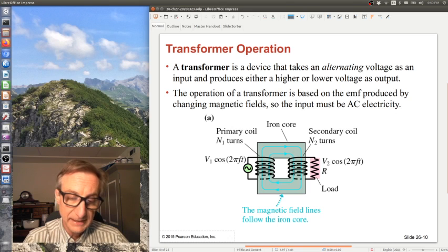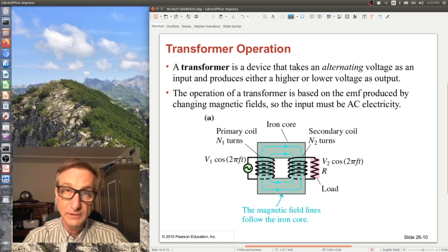So as the magnetic field inside that core is oscillating clockwise, counterclockwise, clockwise, counterclockwise, it's inducing current in that secondary coil that is likewise positive, negative, positive, negative. And the number of turns in that secondary coil determine what the overall induced EMF is. Recall that each coil has an induced EMF delta phi over delta t, where phi is the flux through that individual coil, and then we multiply that by the number of coils because each of those coils adds the EMF up.